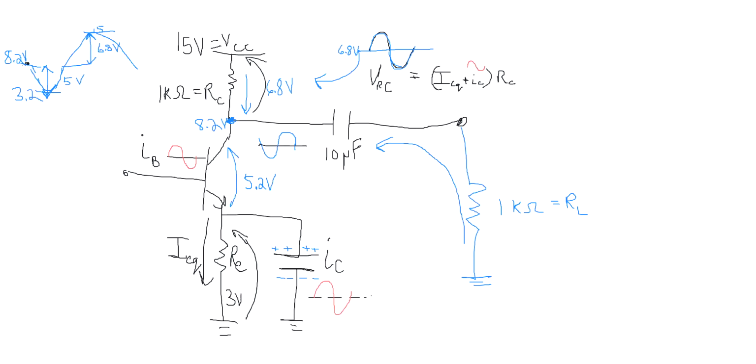So by the time the voltage across the collector emitter has dropped just halfway to 2.5 volts, it's already drawn all of the current that is required by the additional base current.